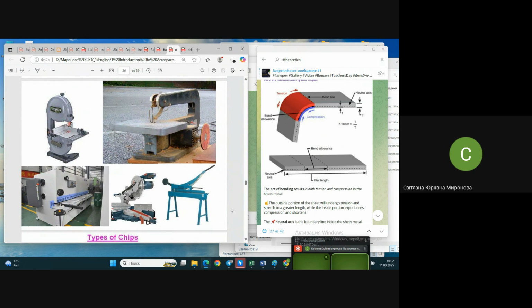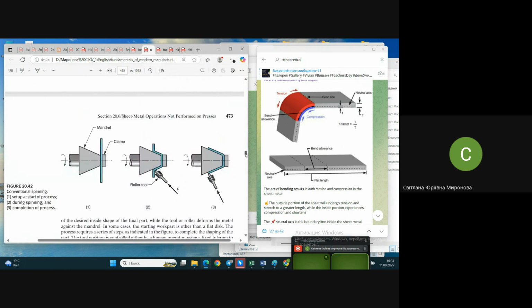Do imagine that you are trying to cut a piece of glass in a guillotine shear. What happens in this case? It's too fragile. It's not cuttable by shear cutting. It will just be broken. And shear cutting means that you direct the force and apply, let's say, the force by shifting the layers of material in a direction perpendicular to the thickness. I hope you have imagined it. For those who have not, let's use pictures.